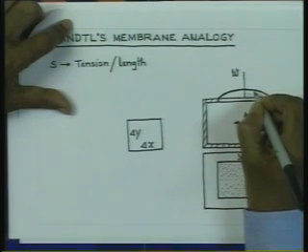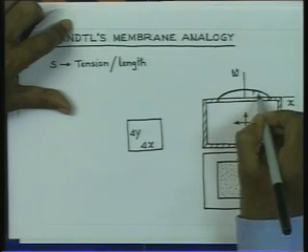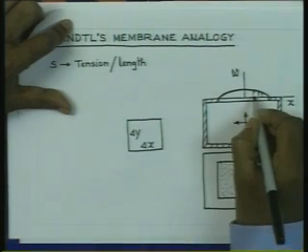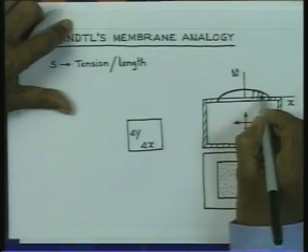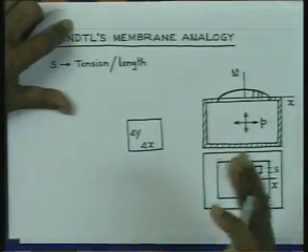Obviously, the membrane is going to be under pressure and the pressure will act normally to the surface, and the deflection of the membrane is very small. So, therefore, we can assume that this pressure is almost acting vertically.